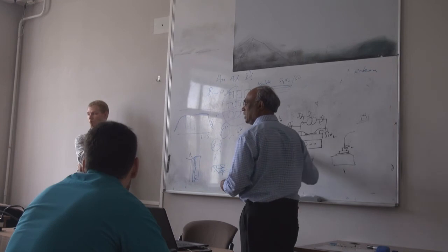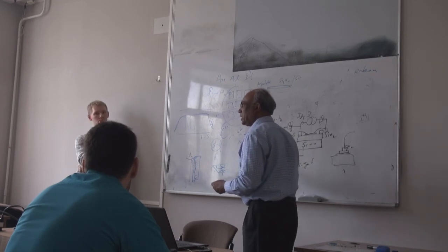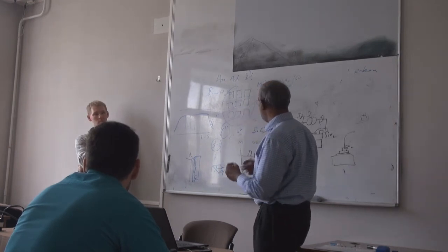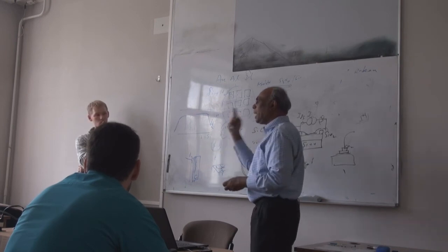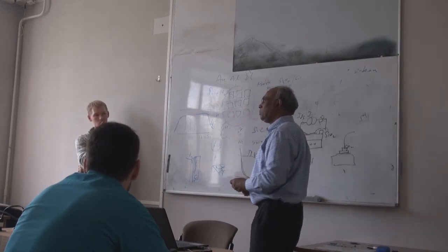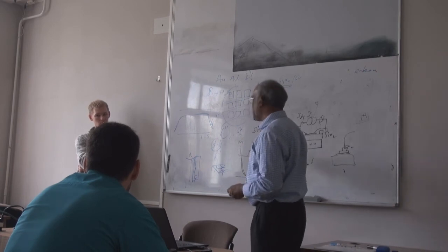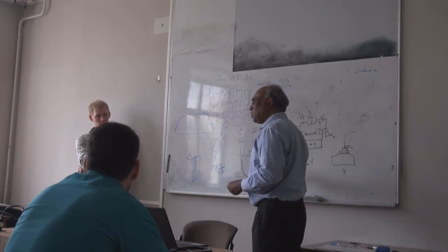I understand. There's no gate dependence, right? Metallic. If they are close enough, they can show ballistic transport. So you can easily tell whether it's semiconducting or metallic by this gate voltage dependence.